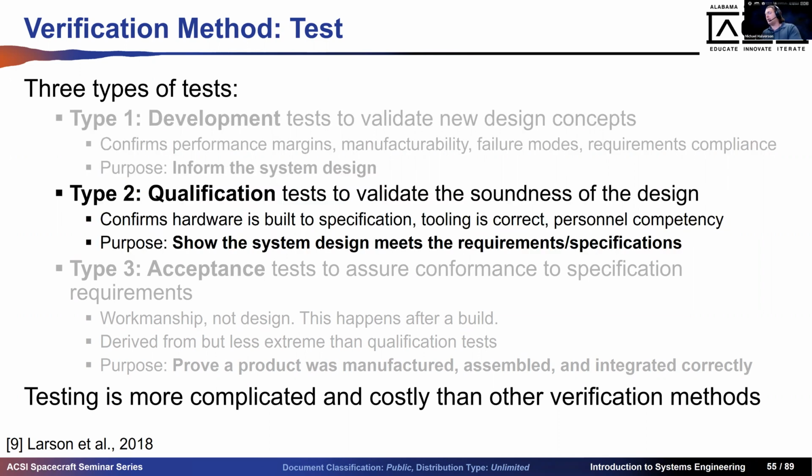Qualification is to understand how the system is going to operate in its intended environment, in the operational environment, specifically the bounds of that operational environment. What is the absolute worst case that this is going to experience? Is it going to survive in that? For satellites, that is launch. That's a pretty bad one for vibe. And for LEO satellites, they'll be going through eclipse, so you'll get really hot and really cold. Plus vacuum kind of sucks. So you've got to understand vibe and TVAC for satellites.